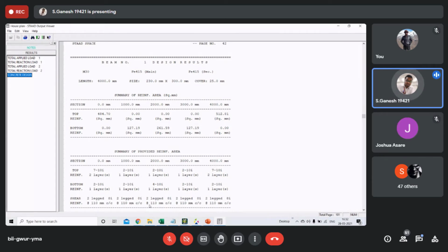And what are the spacings they are using? This you studied in the RCC subject, how you want to design a beam. There you might have studied singly reinforced, doubly reinforced. But when you come and see in the software, it will not show you singly reinforced or doubly reinforced. It will show only a basic result: AST, the moment, the spacing. Our role is to check that AST is sufficient, and the shear force travelling through that beam is within safe limit or not. If shear is failing, then you get more cracks and you need to take care of your stirrup spacings. So these are the major roles of a structural designer when you go ahead.